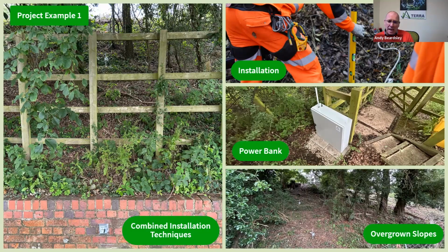The gateway is powered by a 3-battery power bank that lasts for approximately 3 months, and the voltage is monitored remotely. When the voltage reaches the low threshold, the batteries are swapped in a simple exercise that does not require site safety staff, because you can see in that middle right image, the access gate is there and there's the cabinet. So although the batteries are heavy, it's a very quick swap.